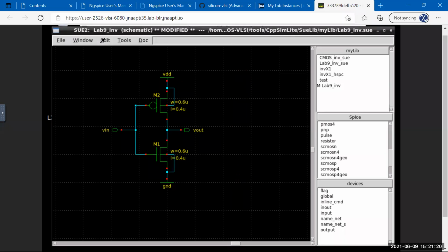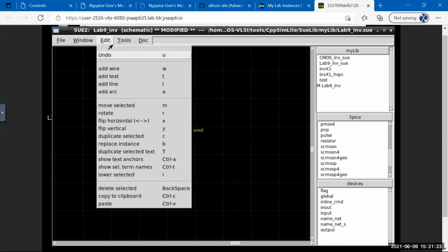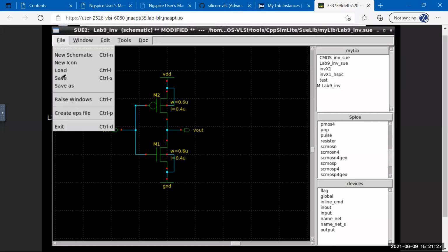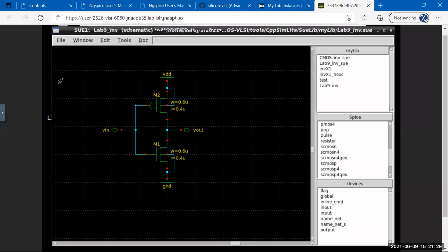Yeah, this SUE2 is not the most bug-free software. It's actually a really old software which Mike kind of took and wrapped some script around. But it's nice for IC design because you can write simple Tcl scripts to create these symbols, export netlists and all that very easily compared to anything open source available.